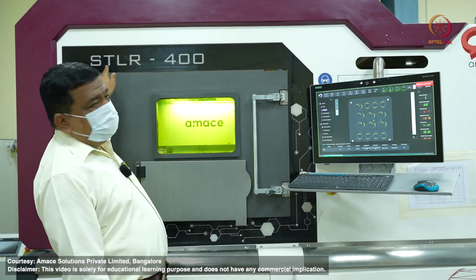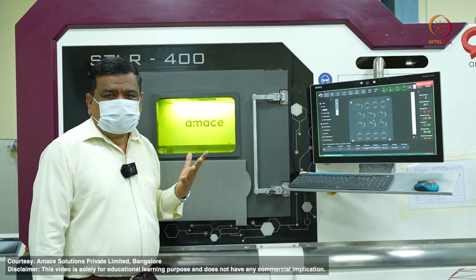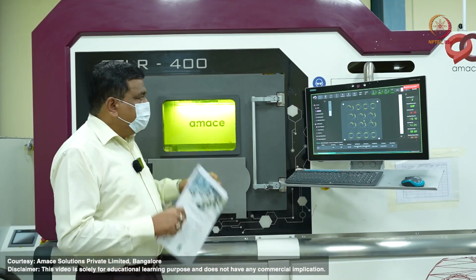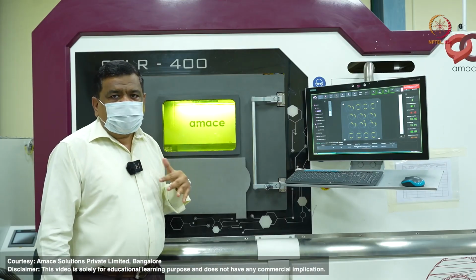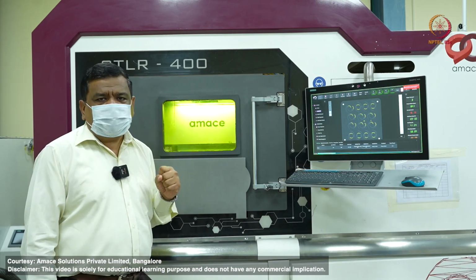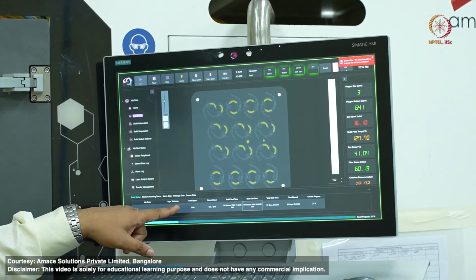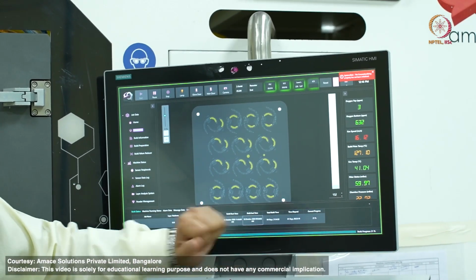Welcome to this STLR 400 model laser powder bed fusion system, which is being manufactured and is currently under operation at MS Solutions Private Limited. This 400 series machine has a powder bed volume of 410 millimeter by 410 millimeter, and the height is around 450 millimeter. Here the layer thickness is 30 micron, and the total number of layers to be printed is 2840. So you can see the build start time, build end time, total build time, and so on.